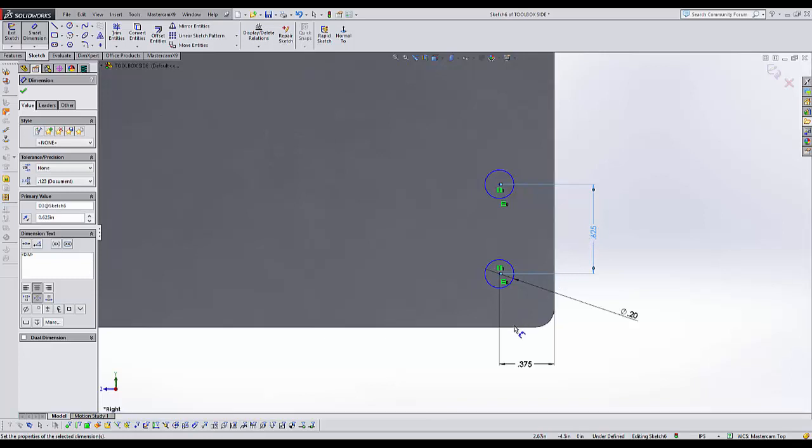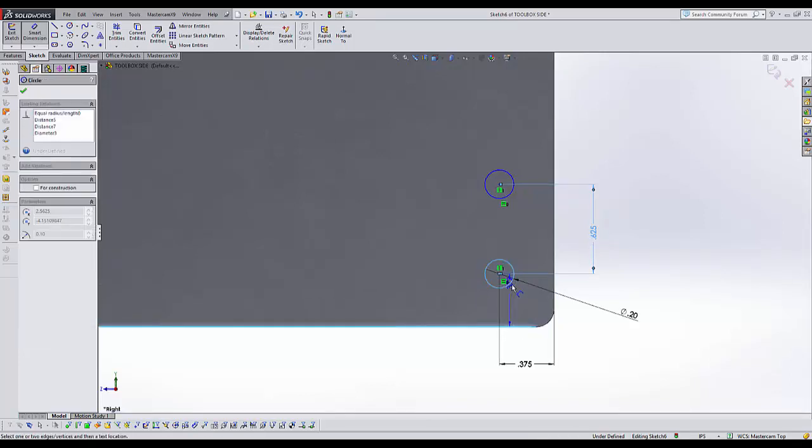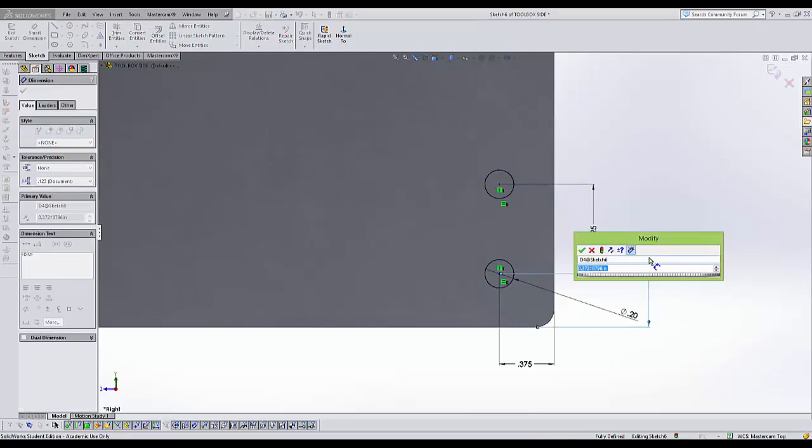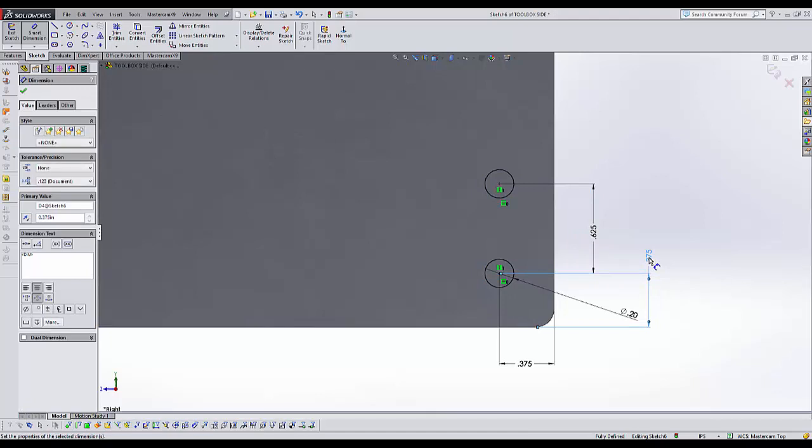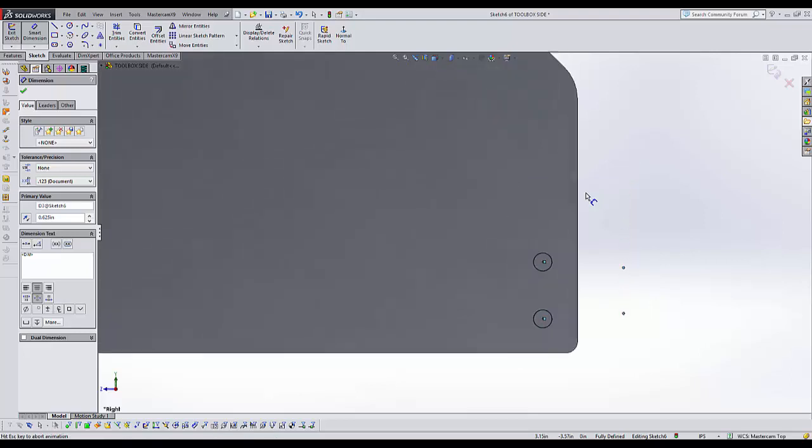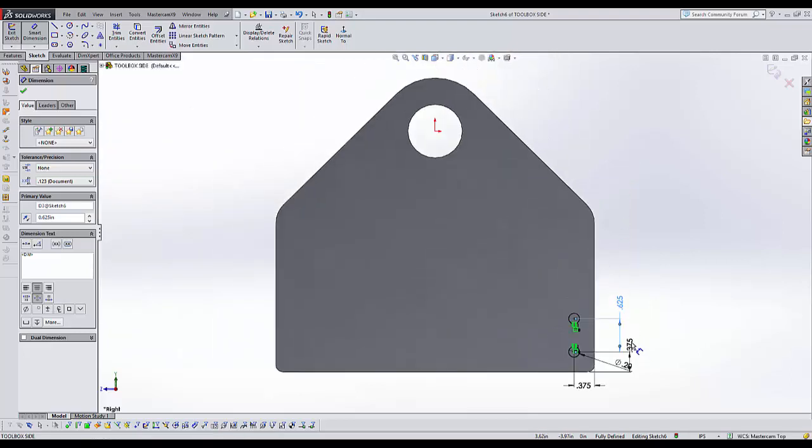Now the last one is I need to lock it somewhere where it's fixed. So it will finish up. It'll be from the edge to the center of the circle. And this one, I'll pull out just a little bit further and above. This one here is going to be 0.375. And what color is this now? Let's make it fit the screen. It is now the color that we're looking for. I'm going to position all my dimensions black. So it's totally constrained.